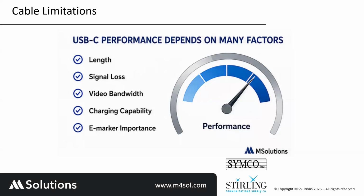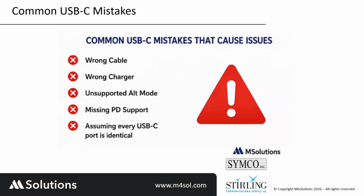In order to transfer the DisplayPort Alternate Mode, which can carry signal up to 18 gig or more, you need to have cable that can support this bandwidth. And it's very important to remember that. Common USB mistake that can cause issue. These are the most common mistake we see in the field.